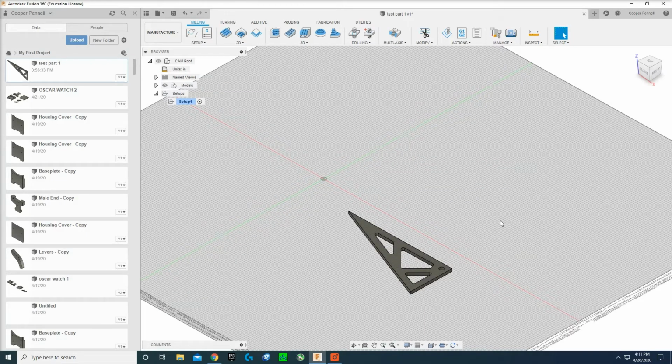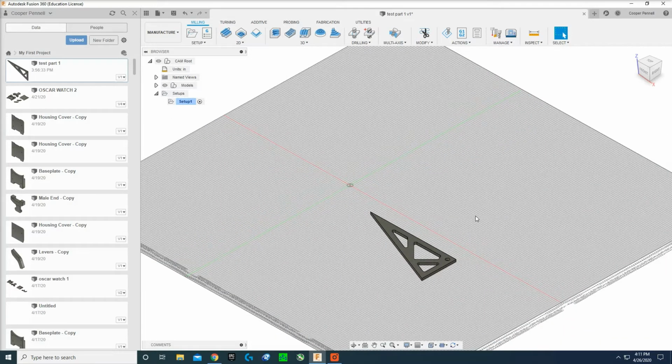I like to machine drill holes first, and then what you need to keep in mind is if you have multiple parts, a part here, a part here, a part here, parts all around in tight spaces, they're going to start vibrating a lot, because as you start taking away material, less material means less strength. So if you have a lot of small parts or parts with big cutouts next to each other, and you're trying to machine huge pockets out with really aggressive cuts, it's going to vibrate, it's going to do really bad things.